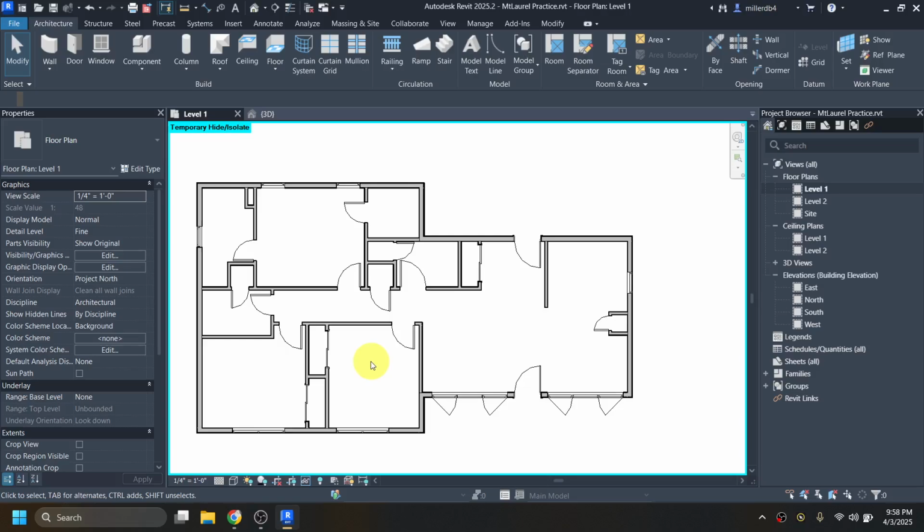The way I do a floor is I'm actually going to do 2 floor systems, with one kind of floating on top of another one. I'm going to make a floor that is just my joist and my subfloor. And then I'm going to make other floors hanging out on top of them that are the individual finishes for certain rooms or areas.